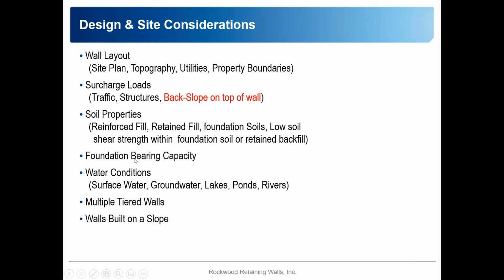Foundation and bearing capacity. On a commercial site, that's typically handled by your geotechnical engineer. They're going to be able to look at and test the stability of that soil. If it's in a residential type setting or application, you want to make sure that it's non-organic, so you're not looking at black dirt, you're not looking at a lot of roots and things like that. And if you're walking in it, your boots aren't sticking in it. So those are kind of the barometers that you would look at. Water conditions.